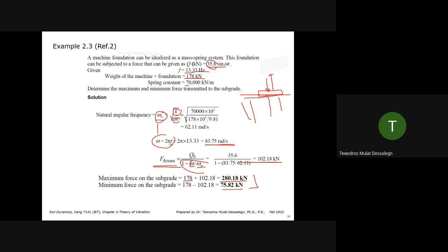But shorter buildings, like 5-story, 8-story, 10-story buildings, completely overturned. They couldn't handle it. Why? Because the natural frequency of the earthquake and the soil was closely matching the natural frequencies of those buildings, between 5 and 10, 15 stories. Taller buildings were not close enough, so they survived.